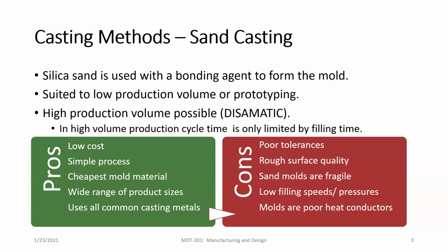It takes time to make the mold because you have to build it around the pattern. You have to make sure it looks good. You have to do some pre-processing of that mold. Oftentimes that includes identifying where the gates and runners are going to be, creating the sprue and the risers and all that stuff. So it is time consuming.